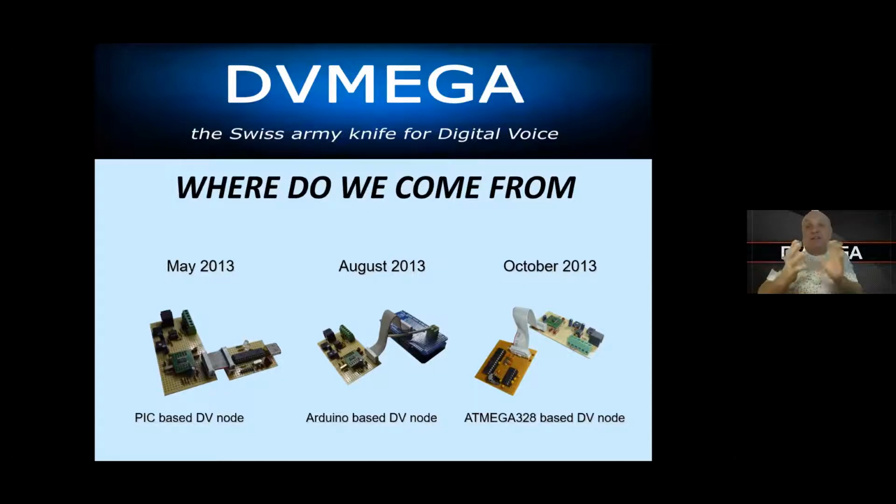In fact, the difference between a hotspot and a repeater is that a hotspot is a simplex repeater. Normally you send your signal to a repeater, and the repeater sends your signal to the network, and it retransmits the received signal. A hotspot is not doing that. The hotspot receives a signal, sends it to the network, and only transmits the data received from the network.